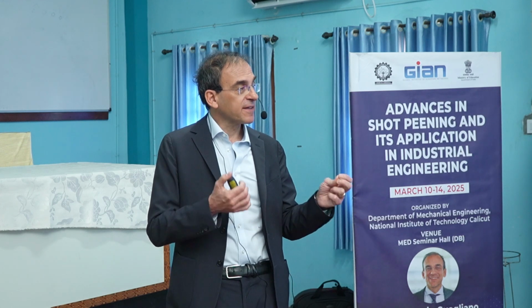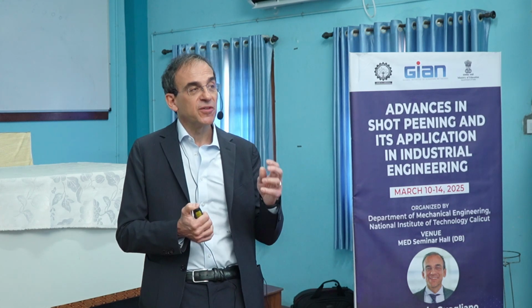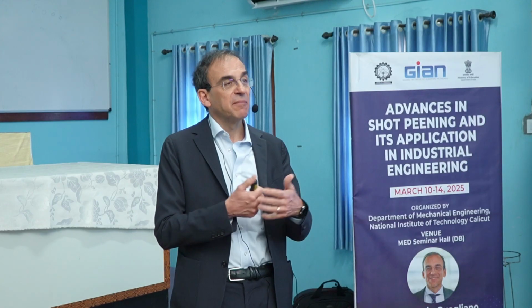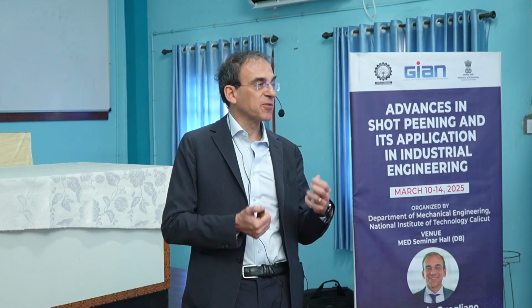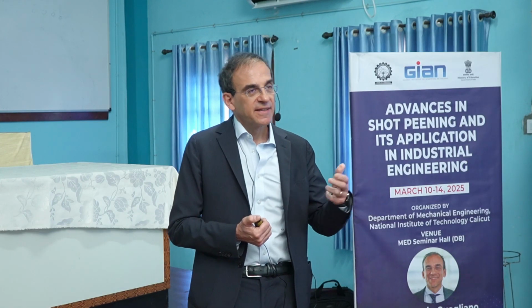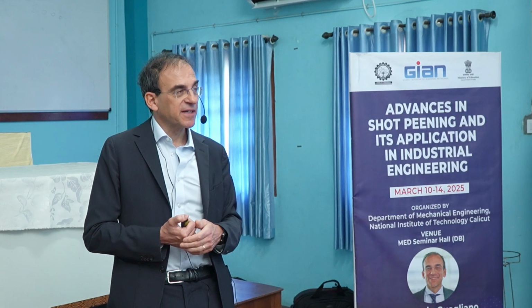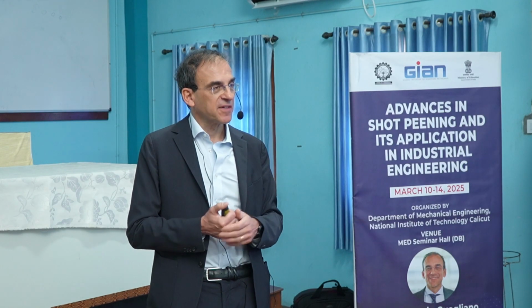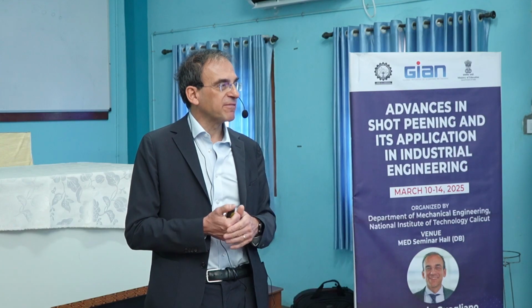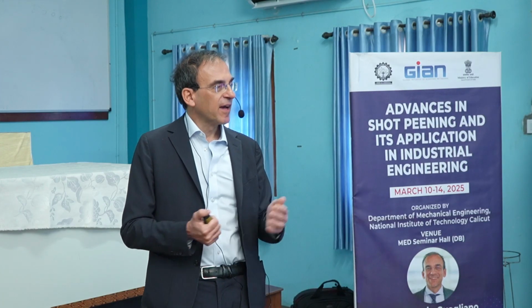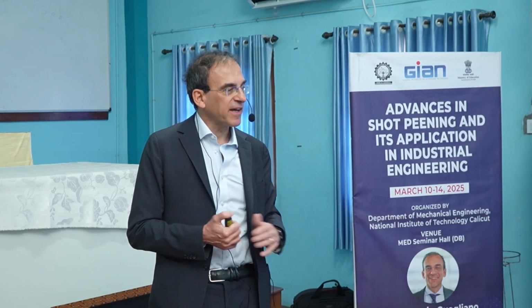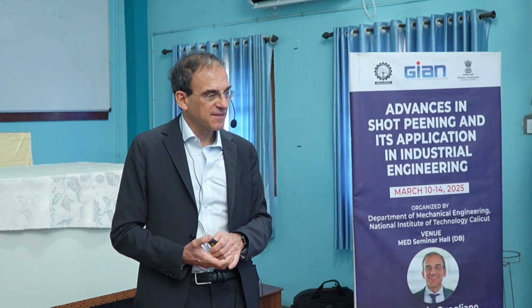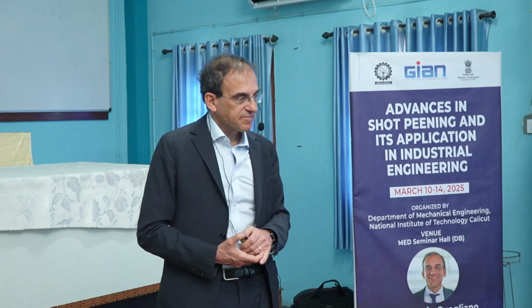Here the challenge is to have this positive microstructural modification without decreasing the surface quality so much. Because if you are using a higher shot peening intensity, it's intuitive that the surface roughness will be increased, of course. And so in the end, we also developed a method that alleviates this effect, maintaining the other ones.